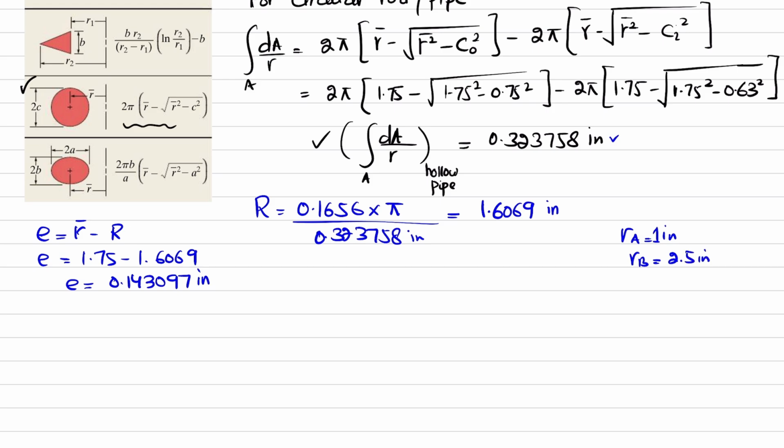Okay. Now we are interested to find out the stress, maximum stresses. So for point A, this stress will be equal to sigma A, and that is capital M into R minus RA divided by area into E into RA. So put the value.